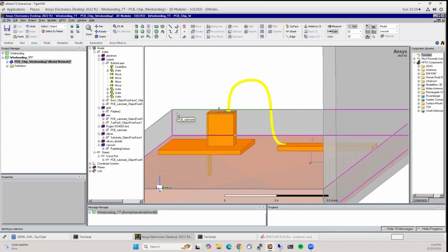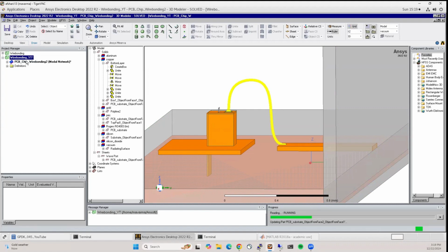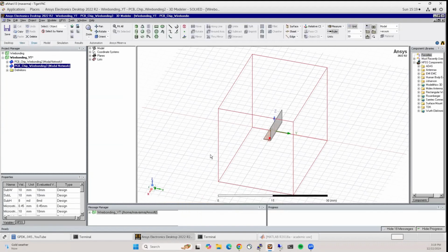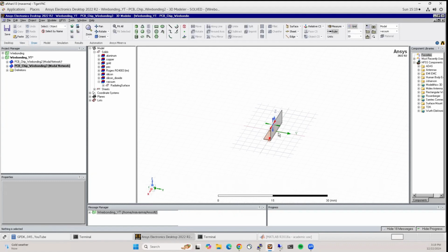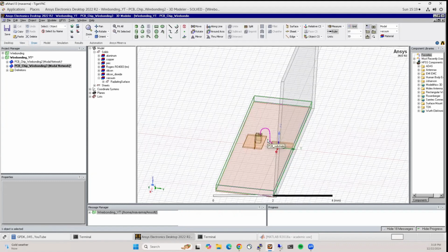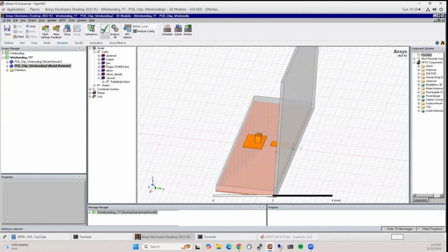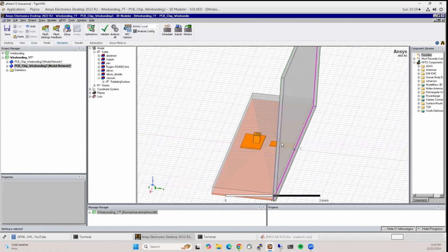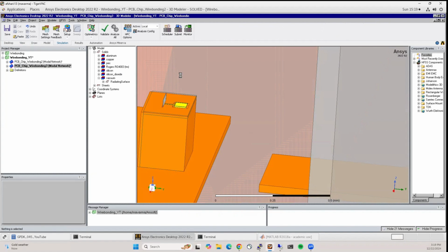And once you have that, you can go ahead and design your circuits. Then at the end, you should always check everything with the full 3D model of everything connected, rather than relying on circuit models. Okay, let's quickly do the pad capacitances. So I'll make a copy of this, and let's go in here and simulate this without the wire bond. That's what I talked about in the beginning of the video.